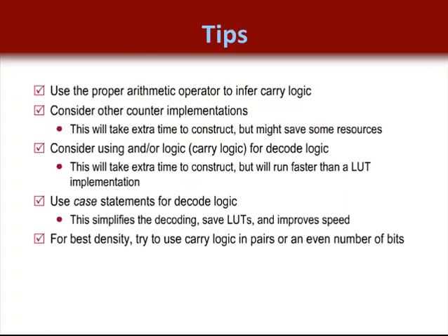So here are a few things you should remember about coding for the carry logic resources. Be sure to use the proper arithmetic operator to infer carry logic. Don't plan on getting carry logic if you define gates, such as the XOR gate. Consider other counter implementations, especially when you have a timing critical path that goes through an arithmetic function.